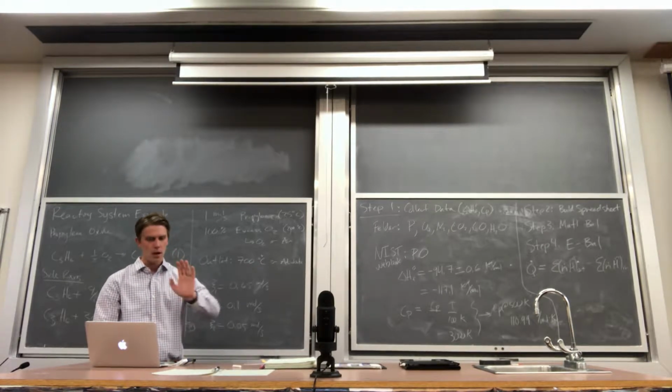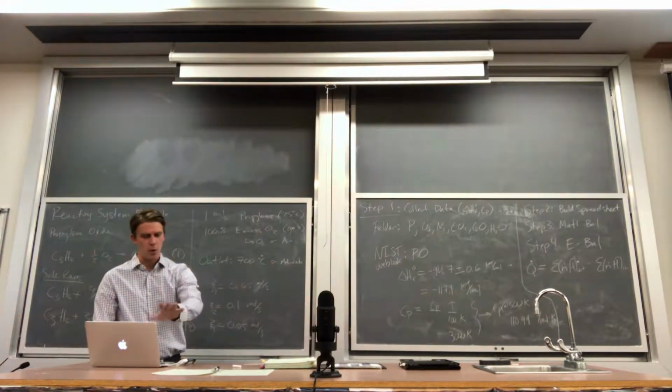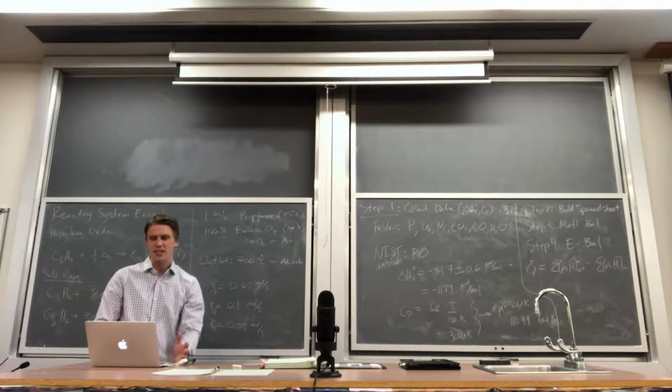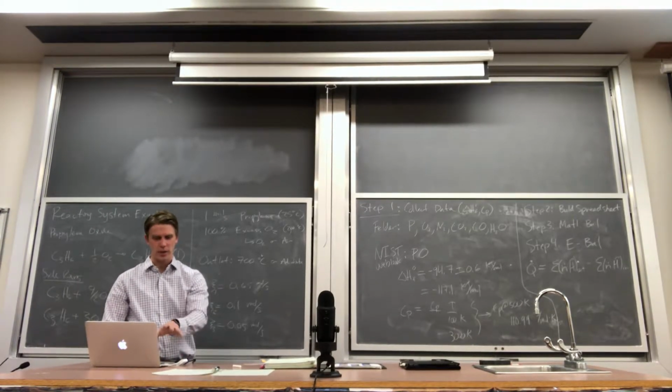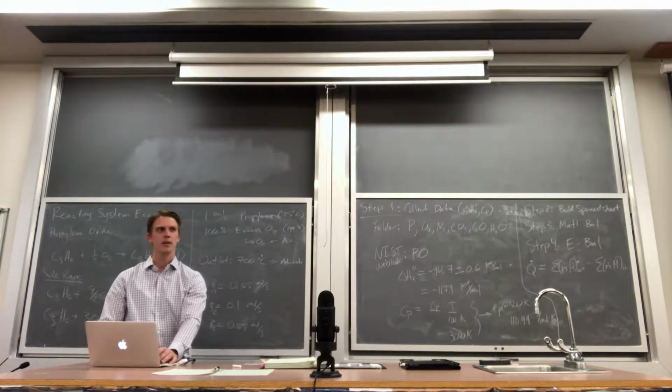So, all of my components in the system. Now the order that I put them in here doesn't matter when I set it up. I kind of did it so that these three components here, the 1, 2, 3, those were the primary species that we're interested in for the reaction. And then here's all the secondary stuff. And then lastly, I put nitrogen at the bottom because it's an inert. It doesn't participate in the reaction.